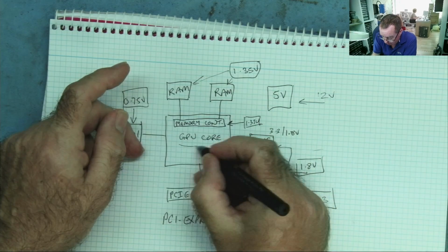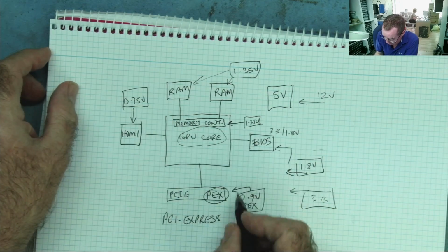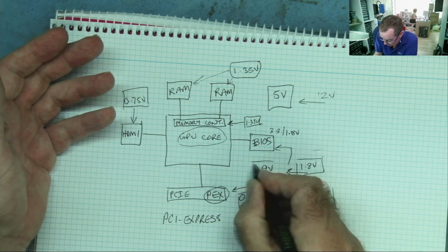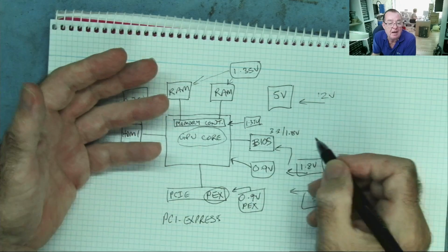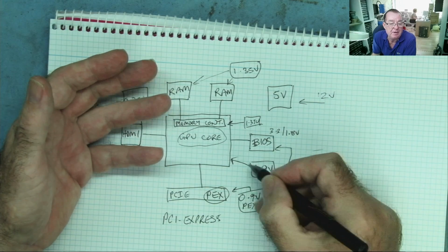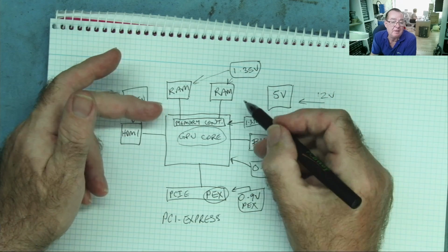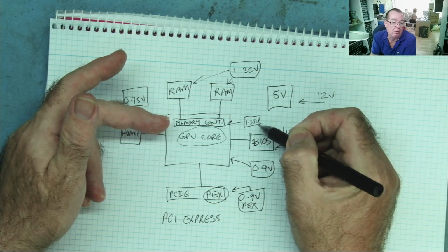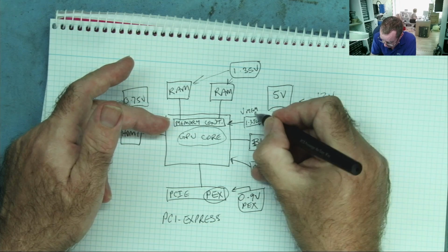And the GPU core itself runs on the lowest voltage, and this is generally 0.8, 0.9 volts, something like that. So the GPU actually has various power supplies. It has 0.9 volts, okay? Because it's talking to the RAM, it either has the same supply voltage as the RAM or something very close. Voltage mem control, okay?